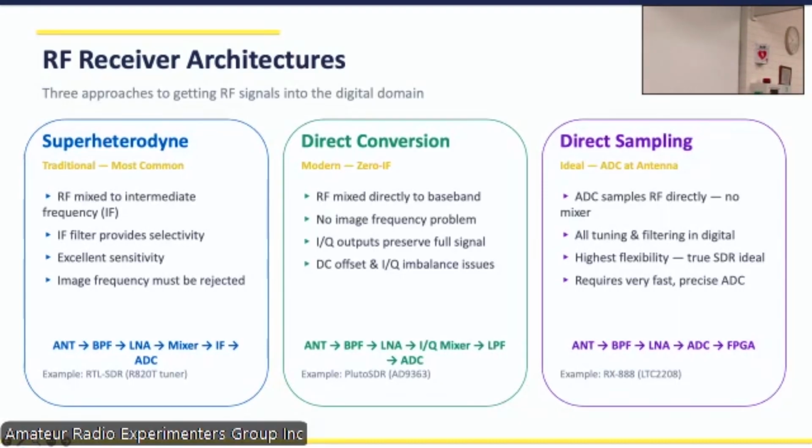So let's just talk about the front end of it. Very important to understand the front end and how it's being used, because this is where we have a lot of problems with software-defined radios, especially the broadband ones, which we look at them. They get overloaded with AM radio, FM radio, digital system, TV, all which are extremely strong signals. So if you're trying to receive in any of those type of areas, you're always going to have a problem to make sure you can keep that signal down below the maximum input to the receiver.